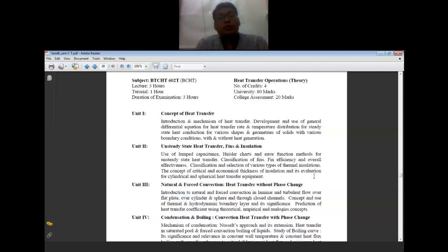This is the basic purpose of the fins, extended surfaces. So we are increasing the surface area. The engine is of this size and has a certain surface area, but when I provide the fins, I attach this fin, I can put different fins so that my heat transfer area is going to increase. And this increased heat transfer area is going to reduce the temperature of that engine.